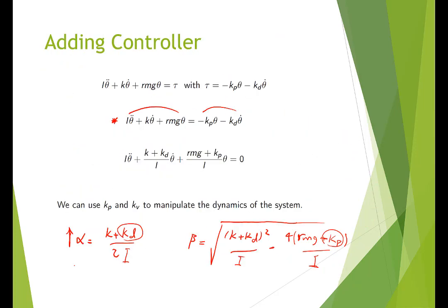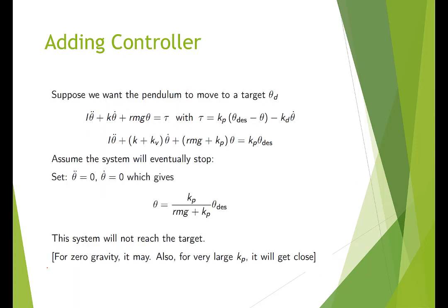Now, we can analyze the equations a bit more. We can consider the equations when we have a spring and damper term. If we write the equations by gathering all the terms for theta, as this. Let's look at this equation and see what happens when the system is stable. Now it became stable at the equilibrium, however it behaved, critically damped, overdamped, or underdamped.